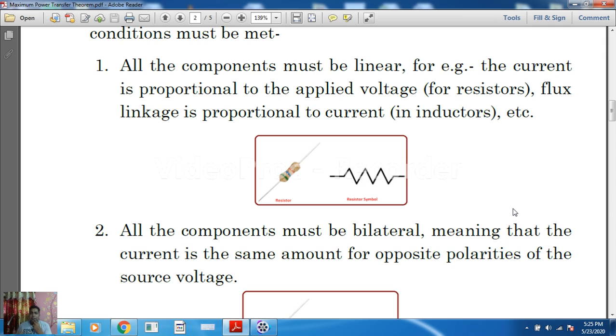What is the linear property or linear characteristic? It is where the V and I property is linear, that means it follows the straight line equation y = mx + c. In an easy way to visualize it, when we increase the voltage value, the current increases, and when the voltage value decreases, the current also decreases. That means V and I.